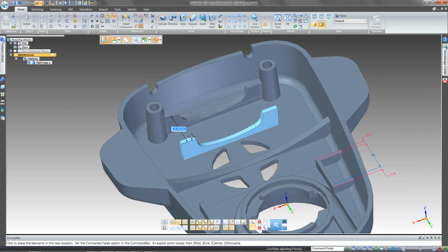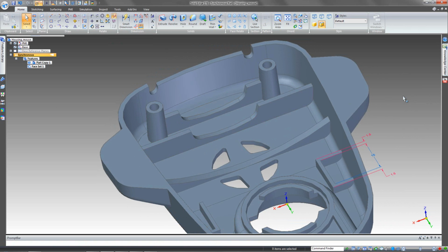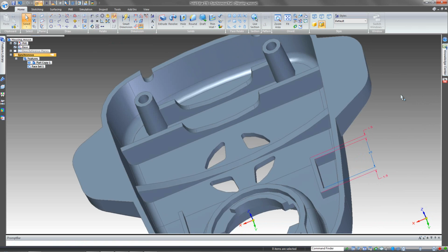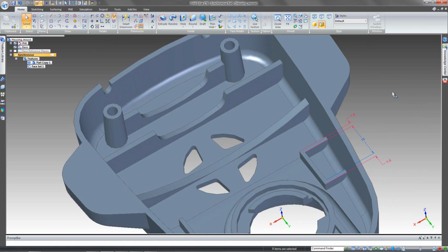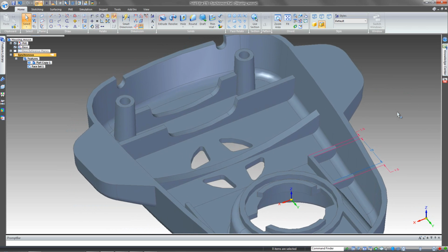But what's nice about Solid Edge is when I specify that maybe I want to copy this, let's say 12 millimeters to the front, Solid Edge is intelligent enough to extend those ribs out to the sidewalls for me. So again, I don't have to close up the ends and then push those out. The system is intelligent enough to go ahead and do that for me.